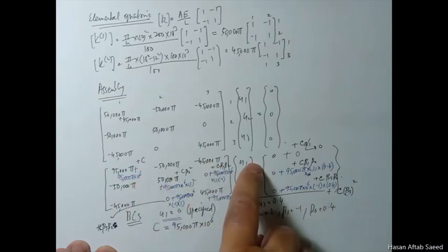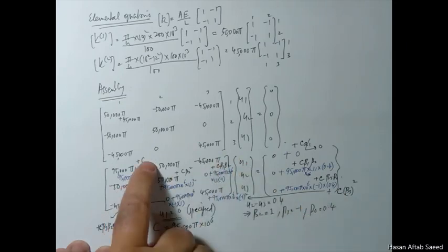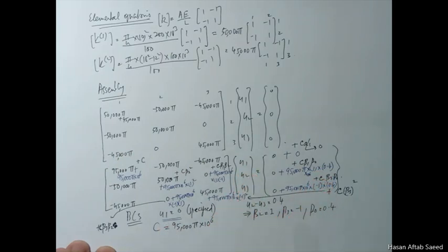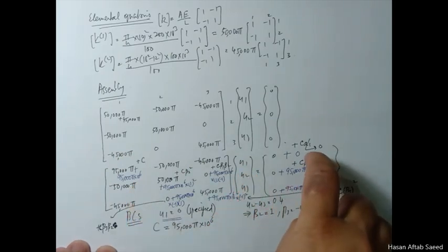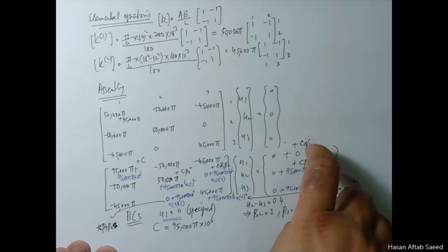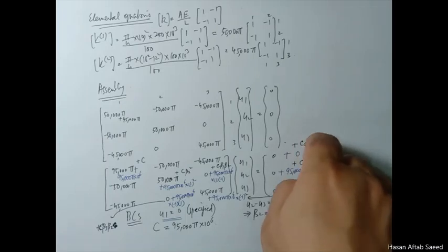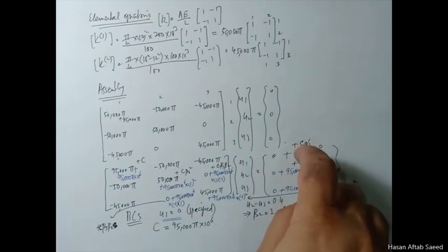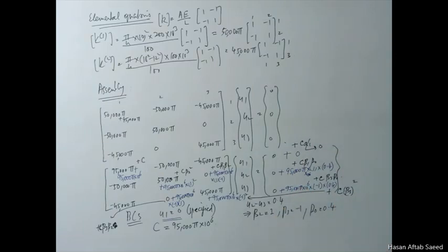The first one, u1, that is a simple boundary condition, so you just apply c here. There's no concept of beta 1, beta 2 or even beta naught here, obviously just one. And on the right hand side you are supposed to add c a1. A1 is the boundary condition that was to be applied. If it was a fixed boundary condition which is non-zero, then some number would have come here, but now it's a 0, so it remains 0. This is how you apply the boundary condition.